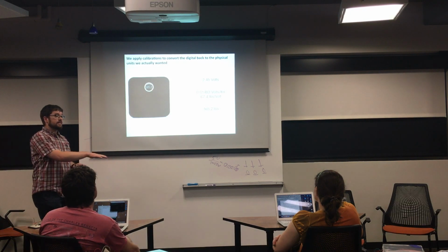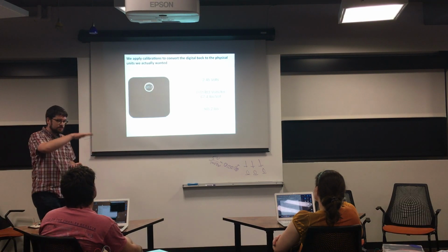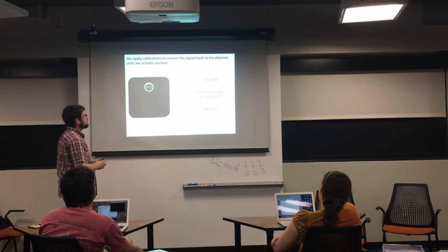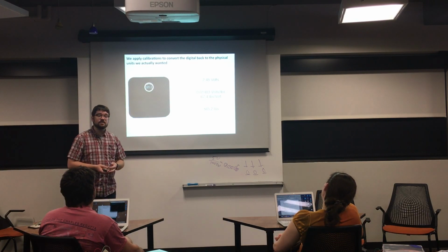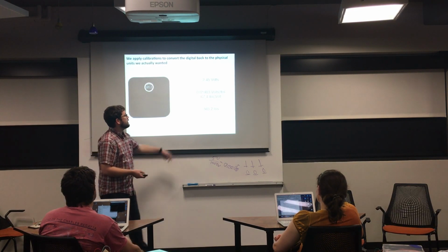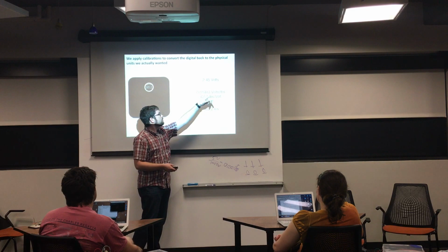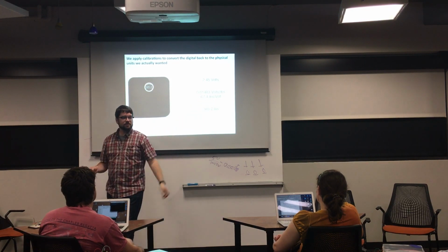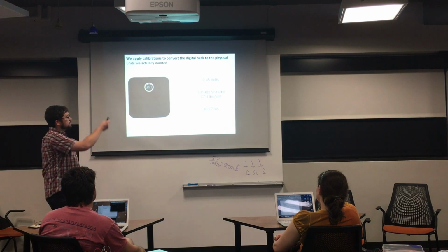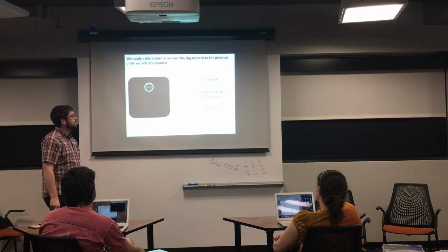So there's a load cell in there. It's just strain gauges, and it's measuring how much you're bending a little piece of aluminum inside. So that 2.45 volts, we need to know some kind of calibration factor that we've done either ourselves, or in this case, the factory did. And let's say it's one of these numbers, either volts per pound or pounds per volt, whichever is easier for you to internalize. And then you multiply the calibration factor, the appropriate one, by the number of volts.